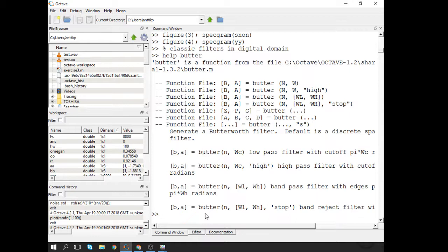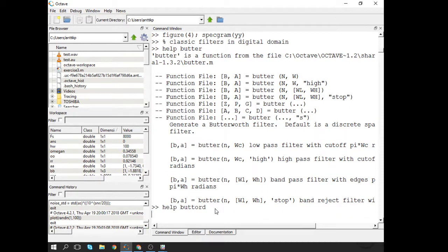Another point you need to define is the stop and start frequency, and what is the attenuation at that point. Okay, so those FC, FS. This is just for generating the filter coefficients, but there's another function to estimate the order number, okay, which is BUT-ORD. So Butterworth order number.